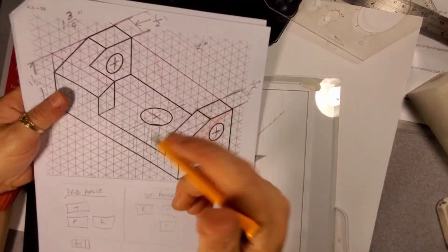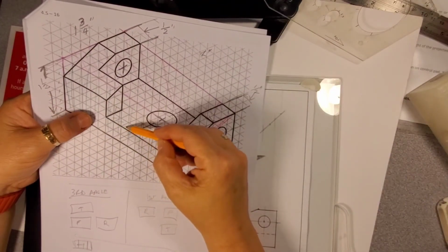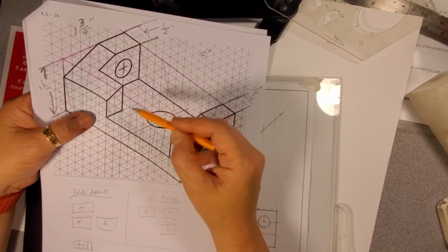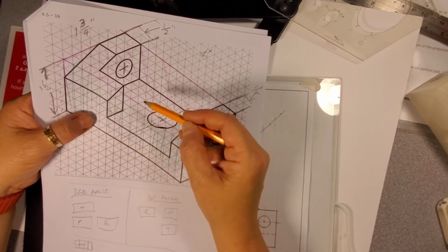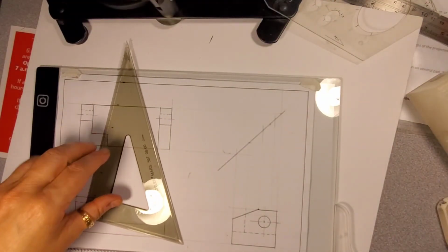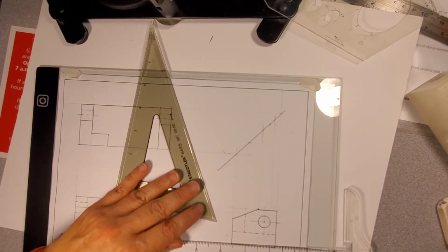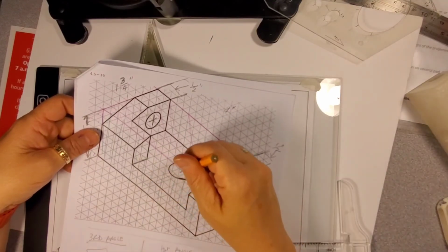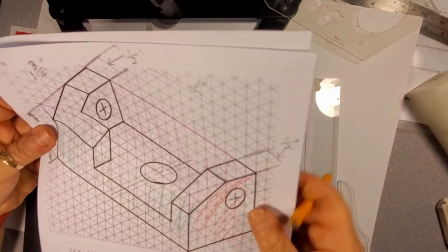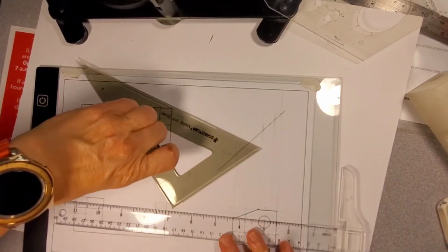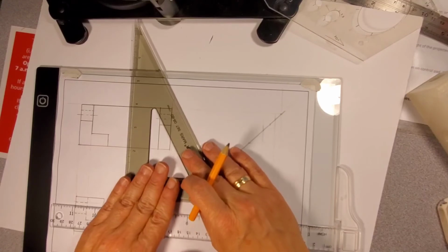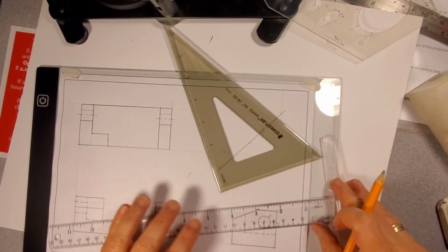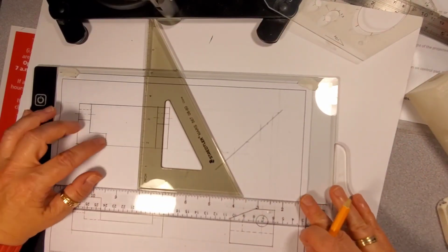Okay, one more time on that one. I see the looks on the faces. 1, 2, 3 squares, and all the way through the center 1, so that's 3.5. If each square is equal to 1/4 inch, half of a 1/4 inch is 1/8 of an inch. That's why. Okay, so that's where the center is this way. The other way, at least it's lined with one of the lines. So it's 1, 2, 3, 4. So it's 1 inch in and 7/8 of an inch from this inside wall.